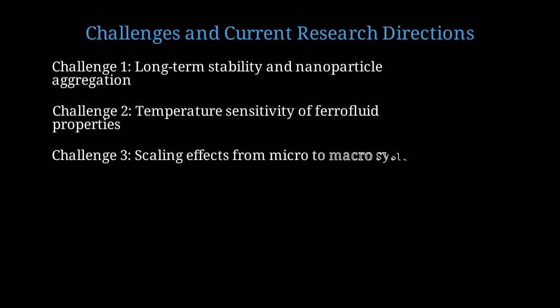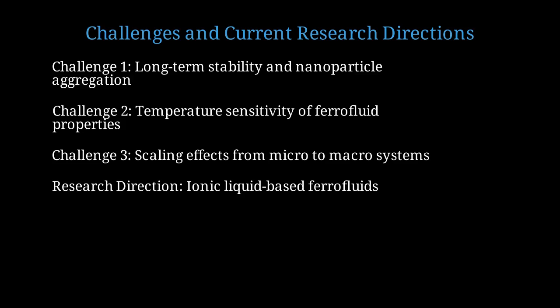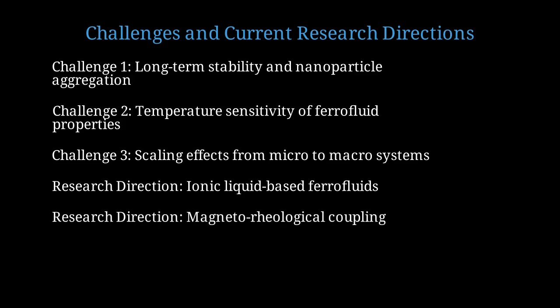Challenge 3 involves scaling effects. Behavior at microscale differs significantly from macroscale due to surface forces dominating over volume forces. One promising research direction is ionic liquid-based ferrofluids, which offer improved stability and wider temperature operating ranges. Another direction is exploring magneto-rheological coupling effects, where applied magnetic fields dynamically alter fluid rheology for adaptive damping.